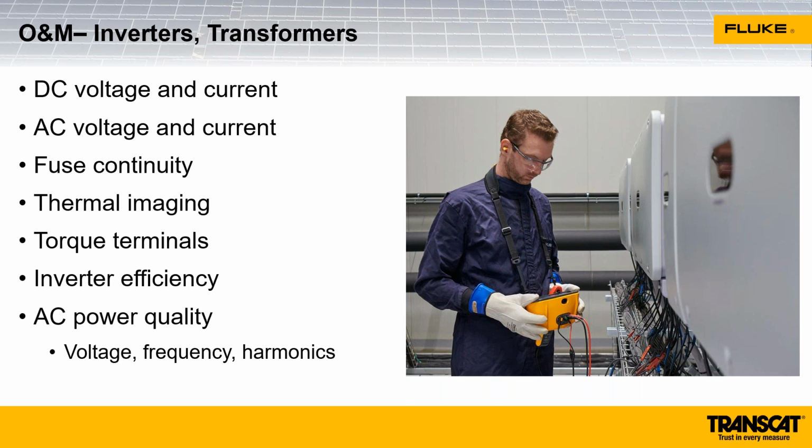You can also test inverter efficiency at that point, and we can do AC power quality analysis as well. We're looking for variances in voltage, frequency, and any kind of harmonics that might influence the operation of the inverter.